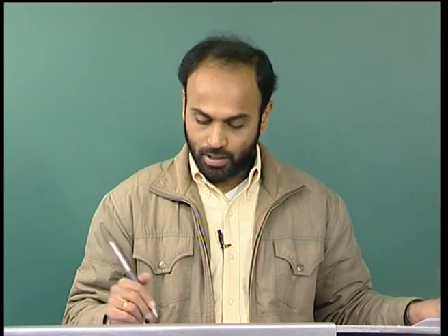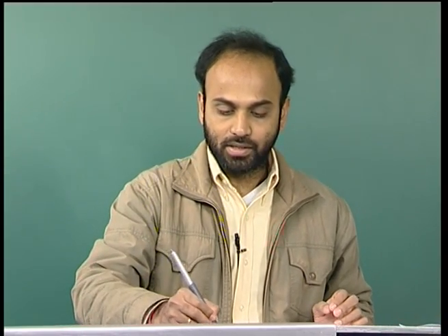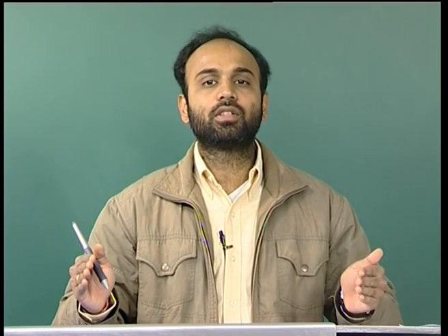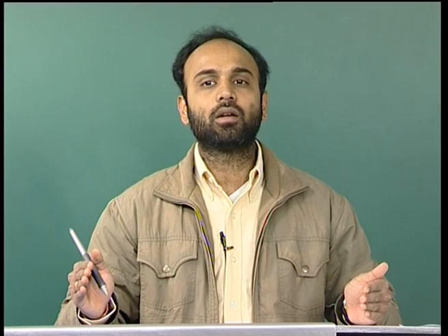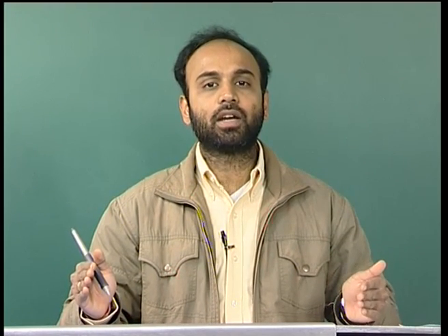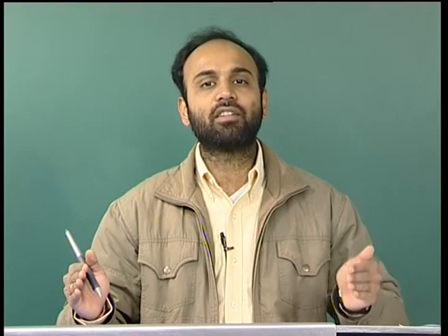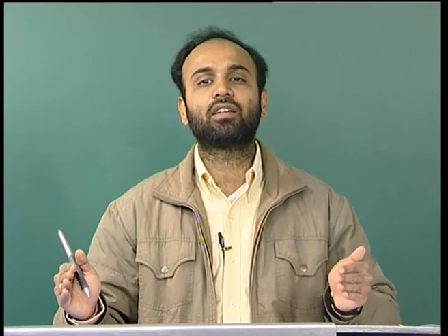Okay. Hence, that covers the basics of OFDM. We talked about what OFDM is and what the motivation behind OFDM is. We introduced the multi-carrier modulation system, and then the implementational problems of multi-carrier modulation, and how OFDM makes the implementation of such a system easier by the introduction of an IFFT at the transmitter and FFT at the receiver.